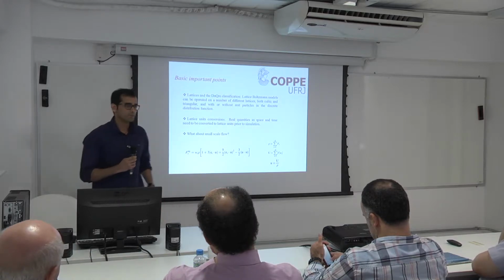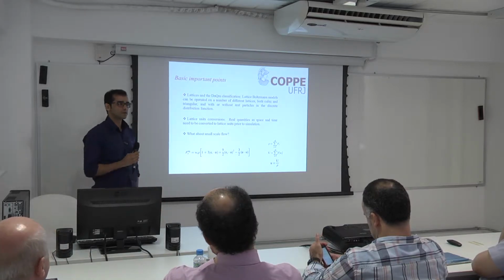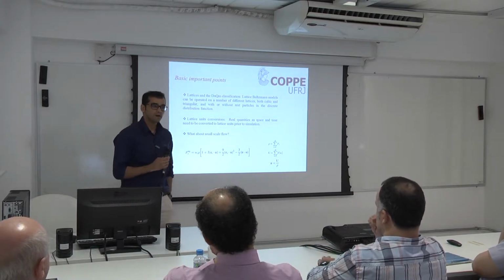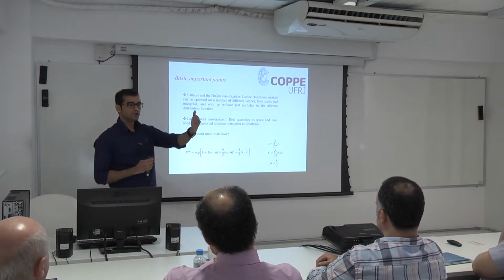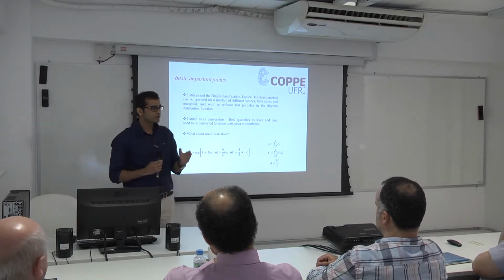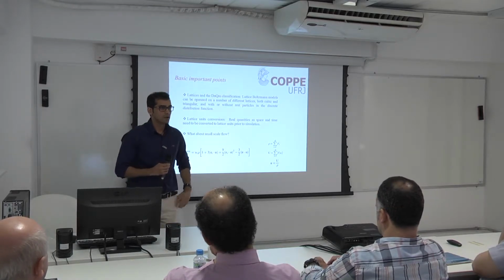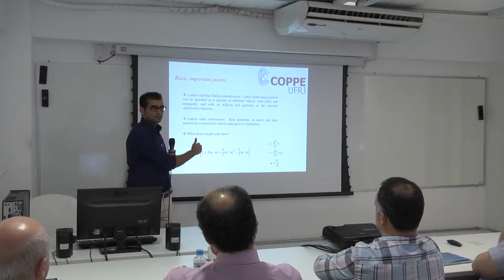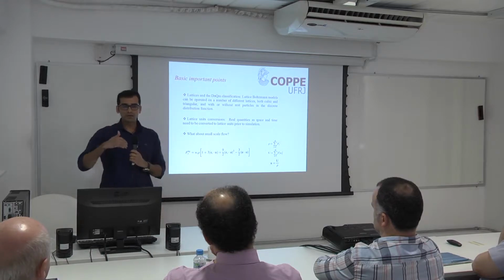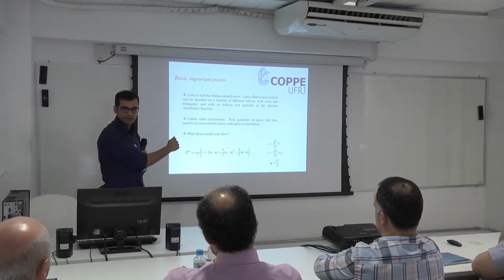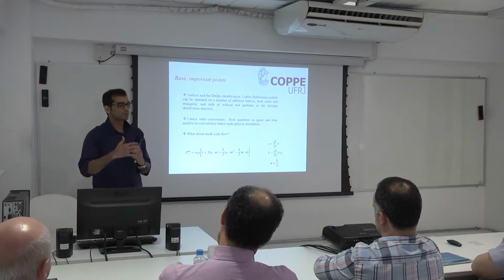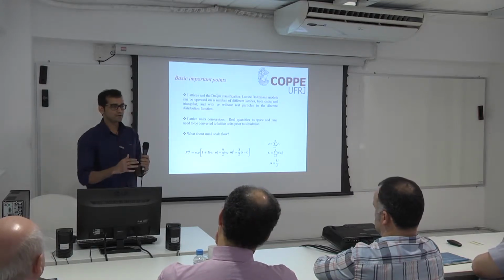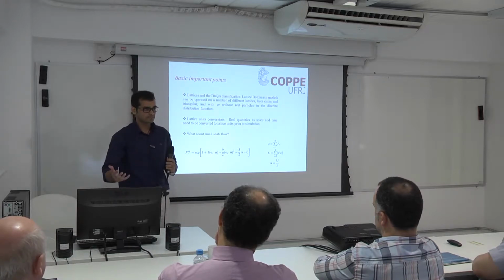Now what happens with the viscosity and Reynolds numbers? Because if we simply increase the Mach number, the viscosity would be smaller and our Reynolds number would not be preserved anymore. So what we need to do at the pore scale, in this case, is increase the viscosity for our Lattice-Boltzmann model so that we can preserve the Reynolds number. So we don't deviate from the principles of physics. That's very important.